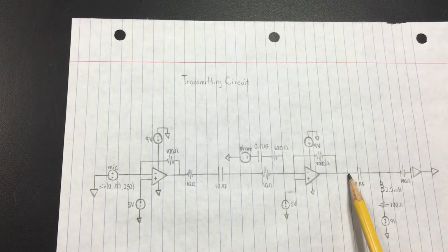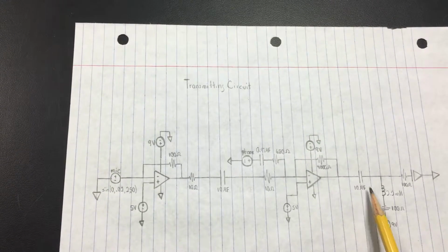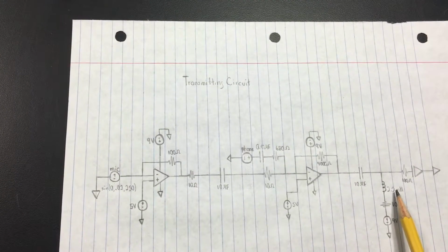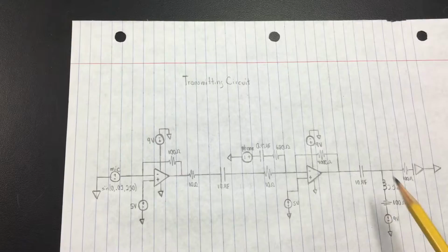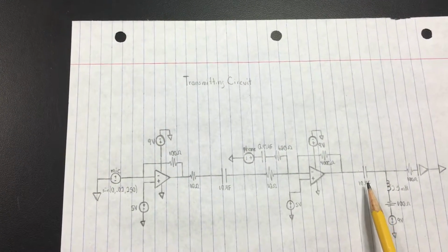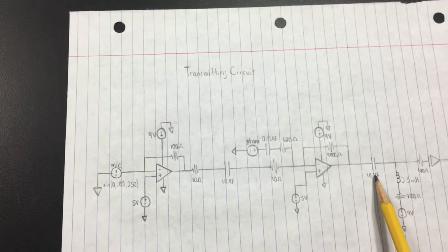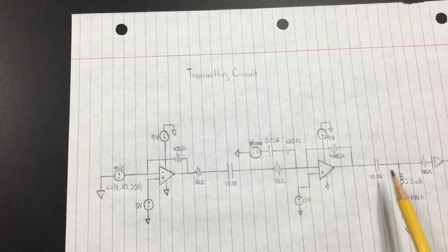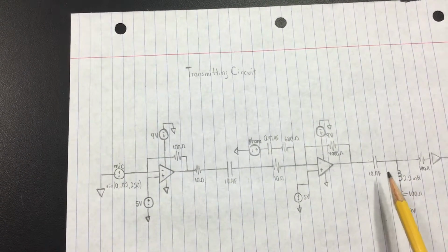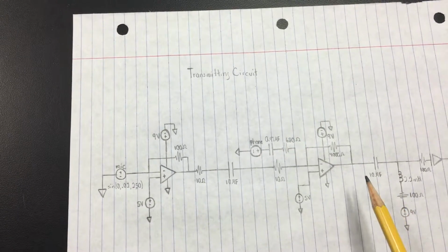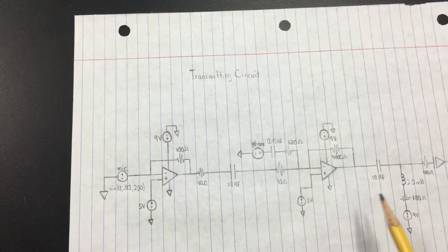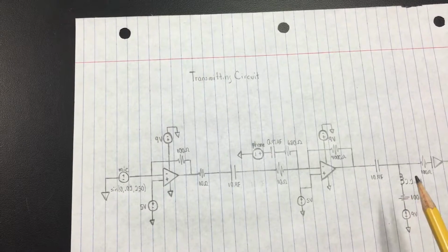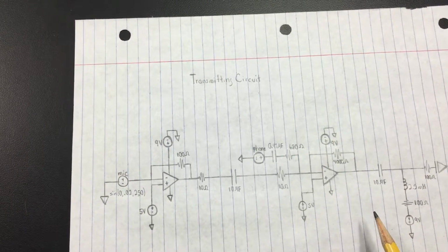And now we approach this 10 microfarad capacitor and 2.2 millihenry inductor. And right now we can see that this component represents a bias T, and a bias T consists of a capacitor and an inductor, which deals with AC signal and DC signal and essentially protects your signal source. In our case, it's the phone, and it also prevents DC current from flowing back.